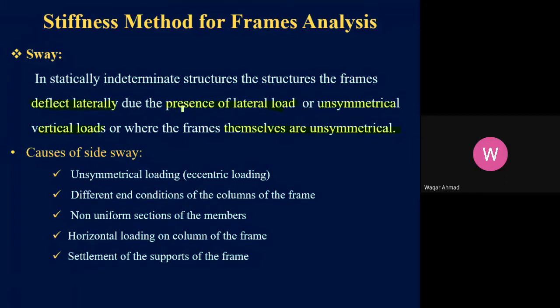What are they? Presence of lateral load. If there is any lateral load present on the frames, it will cause lateral deflection, provided that the support conditions are such that they allow lateral deflection. Or the frames are acted upon by some unsymmetrical vertical loads. So if the vertical load is acting on the frame members such that they are not symmetrical, they can also cause lateral deflection.